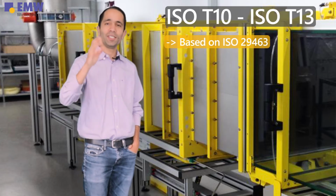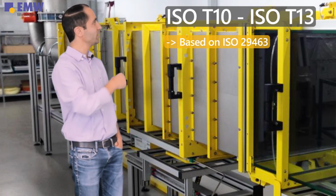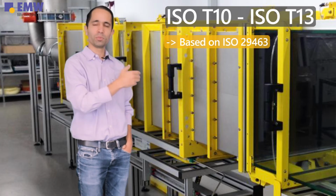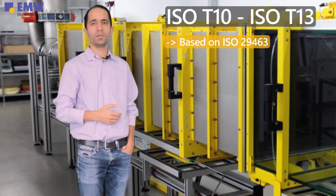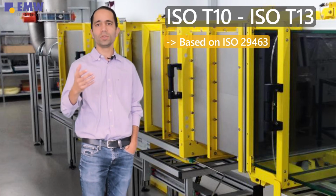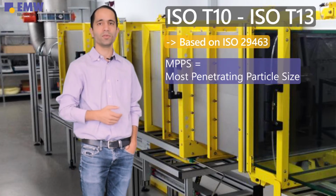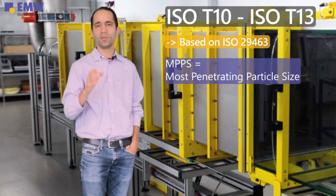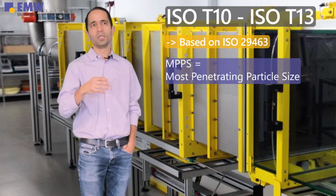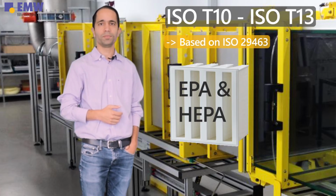So now we have reached the highest level of filter classes according to this test standard, that means the filter classes T10 up to T13. And as I said already, the test procedure for these filter classes is based on the test standard ISO 29463. What we do here during the test procedure is measure the MPPS, the most penetrating particle size of a filter device. And that gives you already an idea that we can compare it pretty much with the well-known EPA and HEPA filter classes in our filter industry.